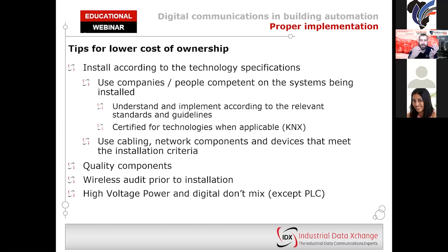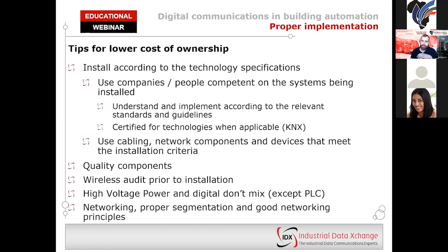This is true in most instances, except for, I've put a point here, PLC, power line communications, where you're actually using your power line infrastructure to modulate a signal between different components in your network. But when running your cables, something that I see all the time is just making sure that you separate your communication cables by a few centimeters from your power cables, and not run them right next to each other, because that very often causes a lot of issues.